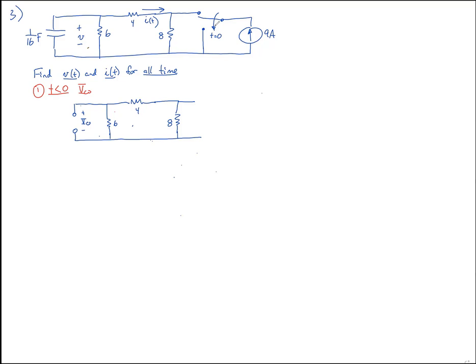What position is the switch, up or down? At t equals 0 it is down. At t less than 0, this is that region that we're drawing it. Time less than 0 here. Oh, at time less than 0, then it should be up. That's right. We always start by drawing it for time less than 0. So it's up. We shouldn't have any switches, no u of t's for time less than 0. We get this circuit.